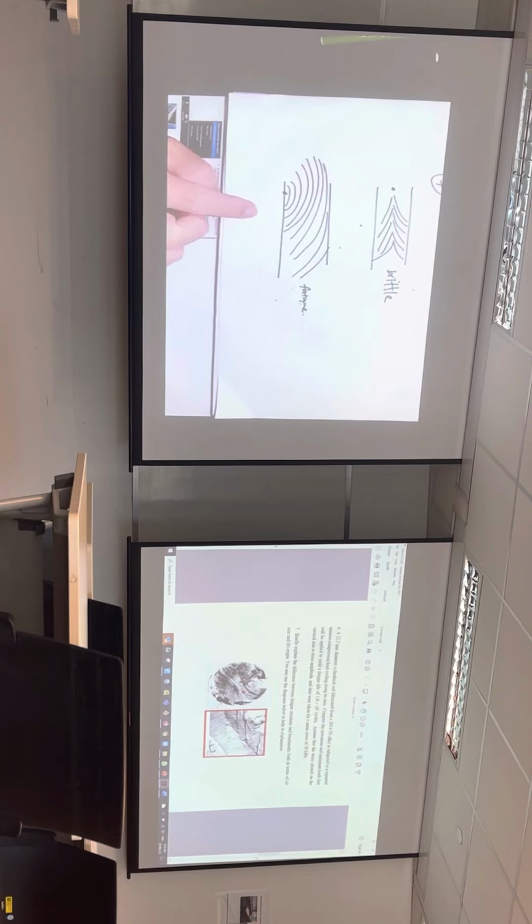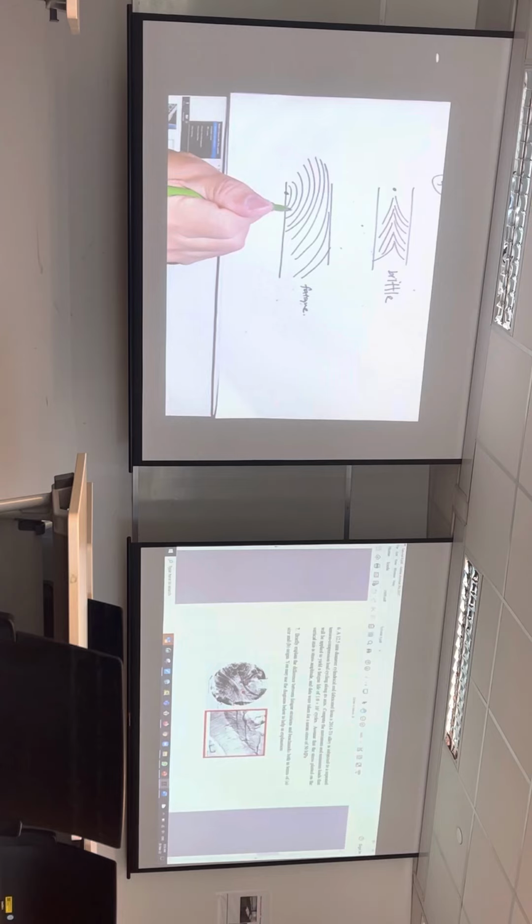In fatigue failure, what really happens is you have a very small initiation crack. Every time, because of the loading cycle, you cause it to open out a little bit, and the crack grows a little bit. When you look at the micrograph, you realize there are many lines.